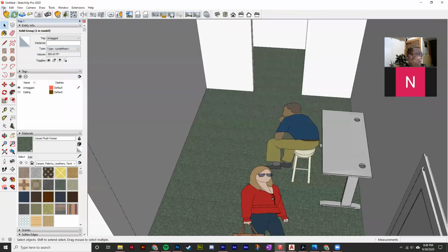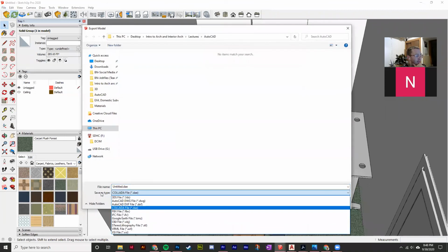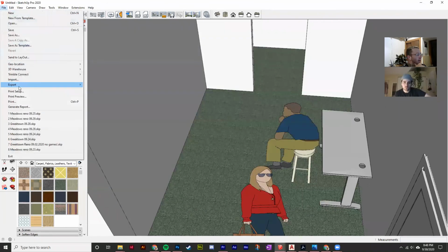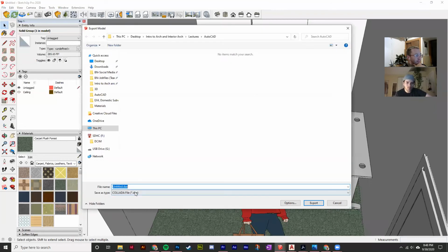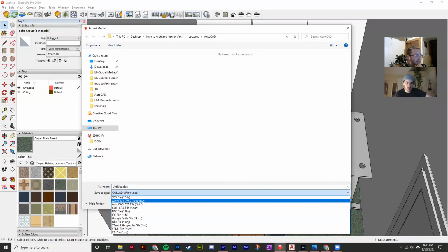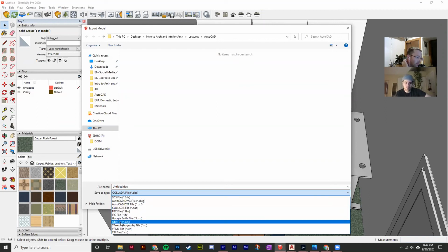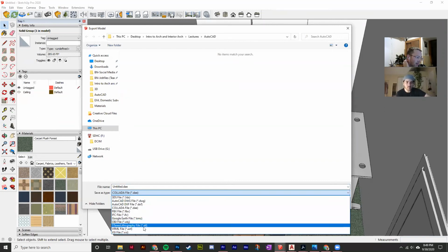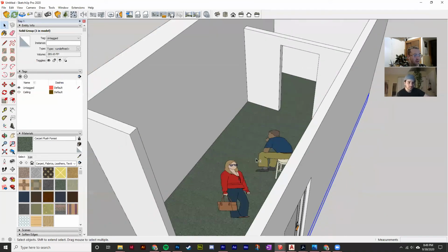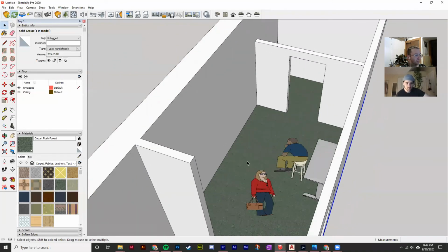To further answer your question, you can also export in different 3D model file types. I just went to File, Export, 3D Model. And you can see you can save as a 3ds, which is, I think, a fairly compatible file for Rhino. You could even open that in AutoCAD, which does 3D as well. There's a whole slew of other file types. I think I've used STL before to downsave models, so that one could work too if you're using a different 3D software to transfer between.